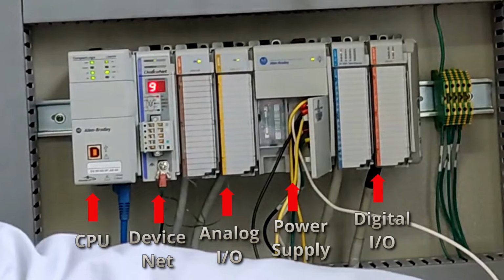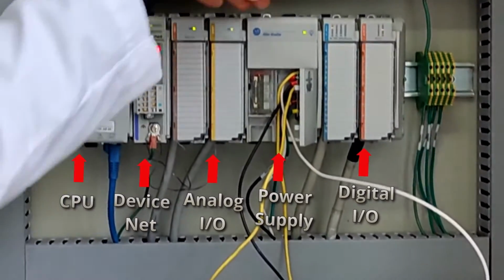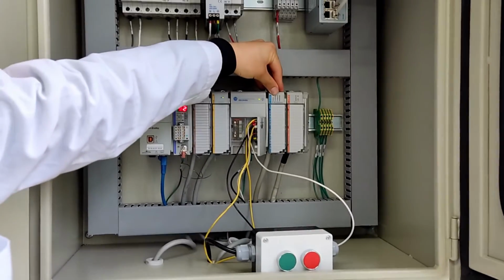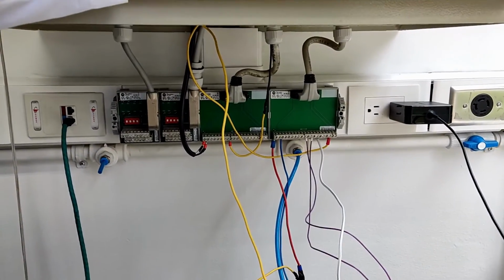For the control of an engine with a variable frequency drive, we use the analog output module 1769OF4. In our project, we also use the power source from Allen Bradley. We can see as well the digital input module 1769IQ16, which allows us 14 digital inputs for our sensors. At its side, we have the digital output module 1769OW8 that has 7 outputs with which we can control our actuators. On the board, we can also appreciate the start and stop buttons. They will be one option to start the whole system.